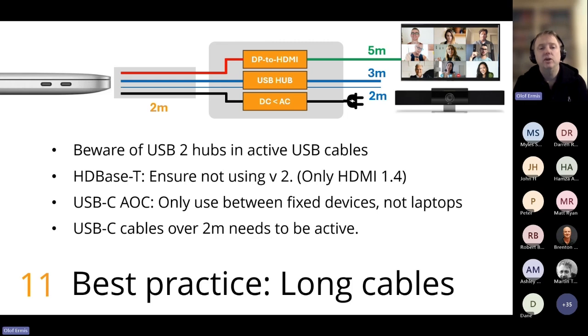And often it works with a longer cable because there are redrivers and retimers in the laptop and the docking station that fix the signal, but that is not the required functionality. So if you are just barely compliant on the laptop and the dock and you have a cable which is longer than 2 meters, there is a high likelihood that it will get lost packets. So 2 meter passive USB-C is always our recommendation for the maximum. If you go longer than 2 meters, it has to be different forms of active technologies, and also keeping track of the charging power.